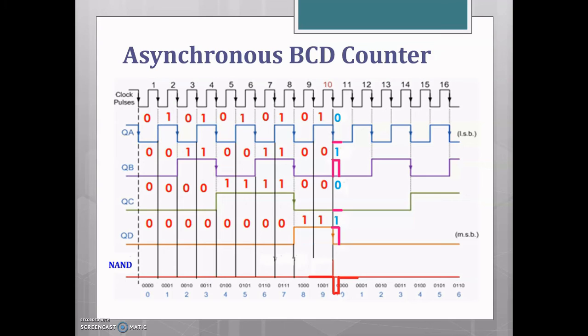Now we can see the timing diagram. For the A flip-flop, you will have the external clock. Initially it will be in the 0 state, and during the first negative edge, the A flip-flop will be active. So toggling occurs. Logic 0 is toggled into logic 1. Similarly, for each negative edge, toggling occurs. So 1 is changed to 0, 0 is changed to 1, 1 to 0.